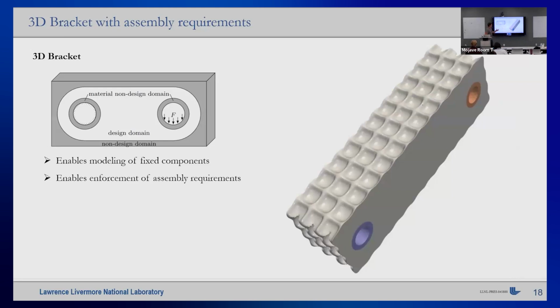And we said, okay, if we have this multi-material approach, we can model these 2 circular structures through a different level set field. We can model them through a separate level set field, and then the middle part of this bracket is, in this case, our design level set field. So this is either 3 level set fields, one is a design level set field, the other 2 are basically constant, but we could also just allow them to move by defining them through 2, 3 defined parameters.